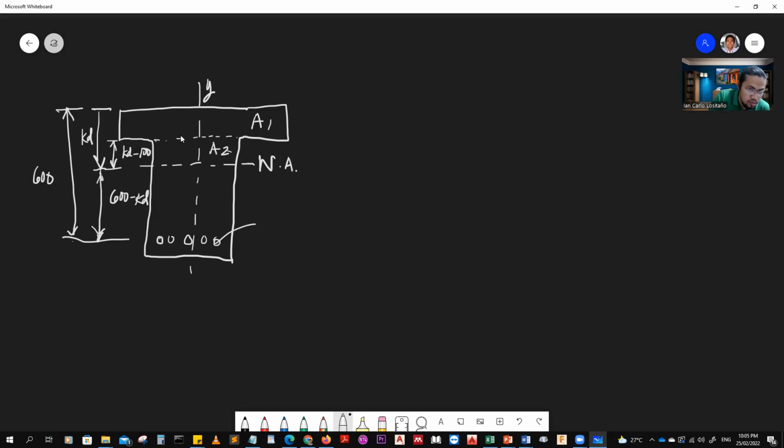So A3 is actually n times Ast, as I was saying a while ago. The n proves to be useful. It's going to be 8, as identified. 8 times the Ast is 2,400 millimeters squared. So this becomes 19,200 millimeters squared. We have to find A1 and A2.